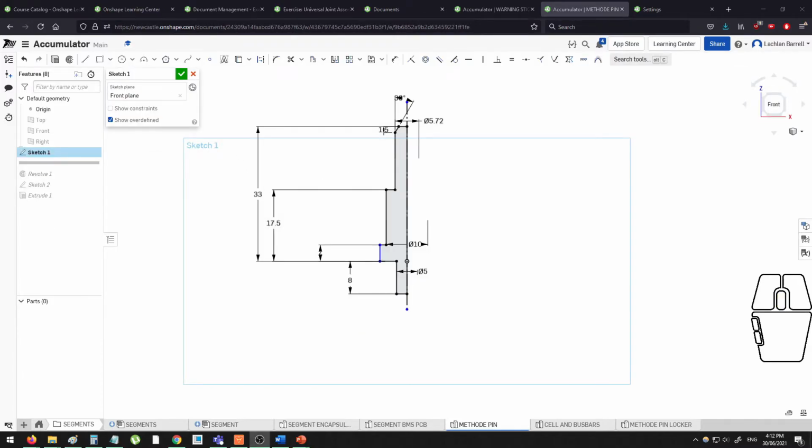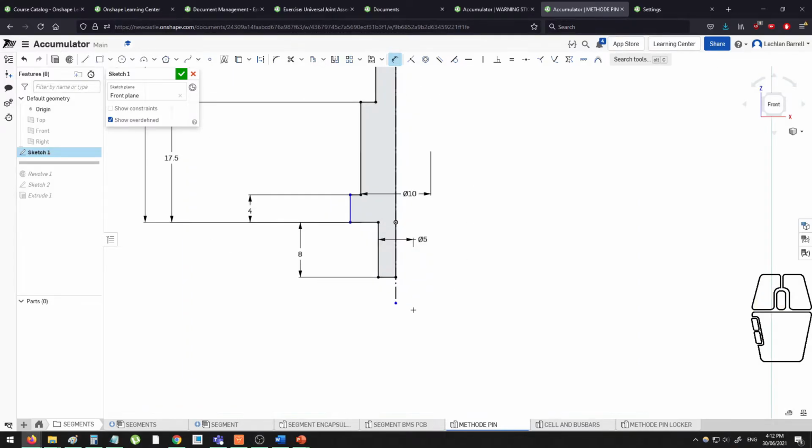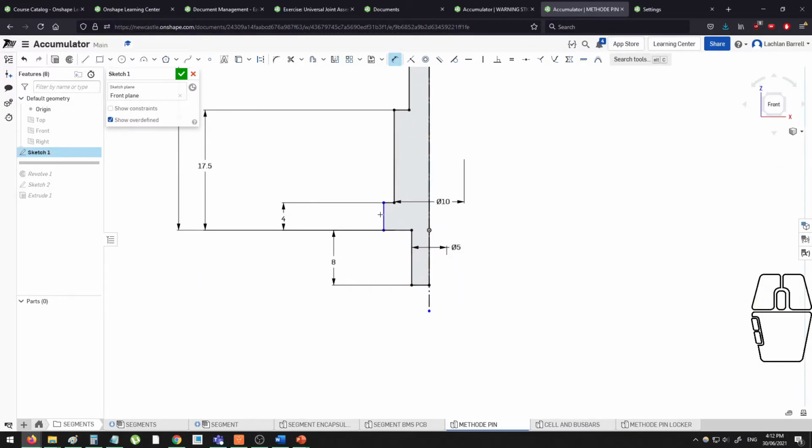So the last interesting tip about revolves is how you can use the dimension tool when you have a construction line down the middle. So if I just dimension these as normal, you can see we get a 6.5mm dimension there, which is fine. However, since this is going to be a revolve, it can actually be fairly logical for me to want that as a diameter instead. So if I've used a construction line, like I have down the center line there, and I take this dimension beyond that construction line, you can see it actually uses a diameter dimension instead of a radial one.